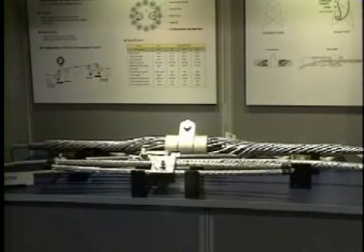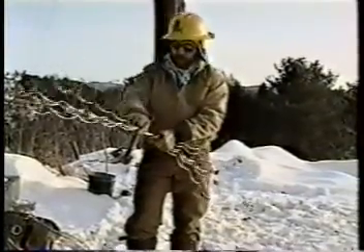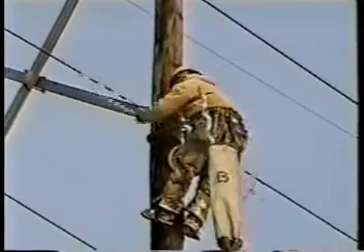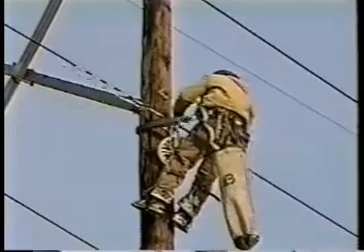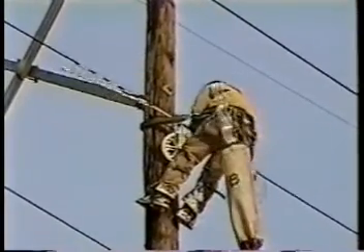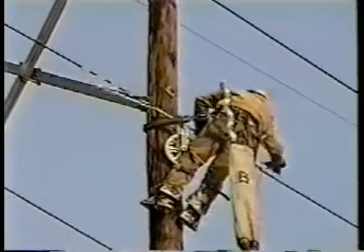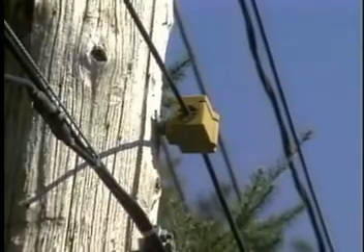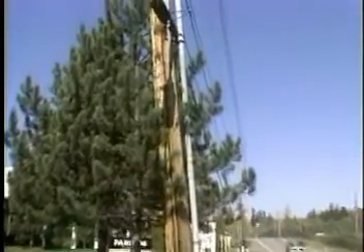These grips consist of a strain relief placed around the cable to which a series of twisted interlocking rods are added. The rods are center marked for correct alignment and are snapped into place sequentially over the strain relief and cable. When complete, a clamp is secured over the center of the grip and attached to the pole or tower. When using ADSS cable, special clamps are used to gently grip the cable with compressible rubber inserts. When the pole is very close to trees, or if there are conduits running up the pole, it may be necessary to mount the cable clamp on an extension arm to give the required clearance.